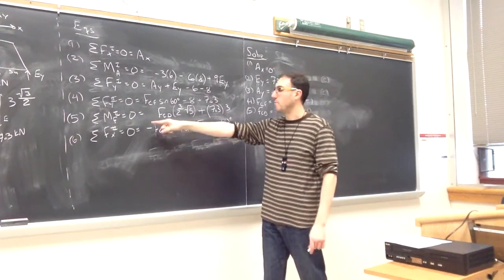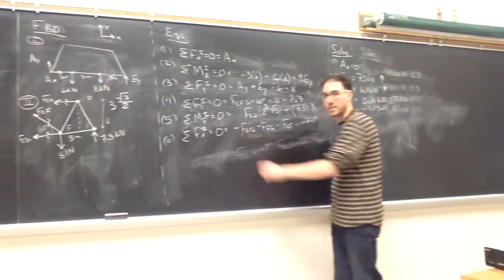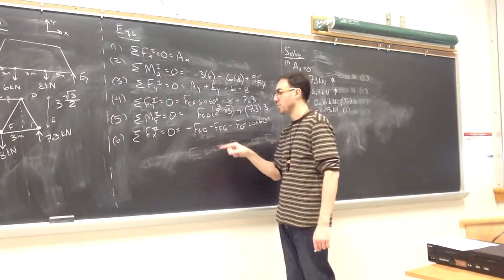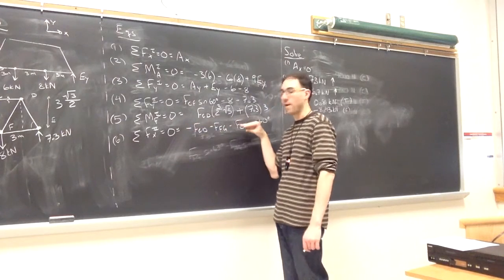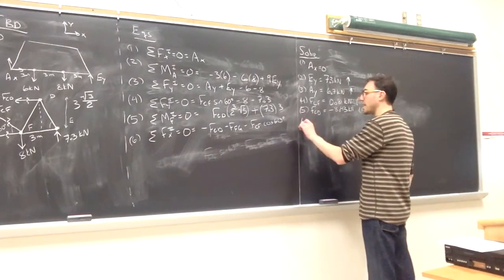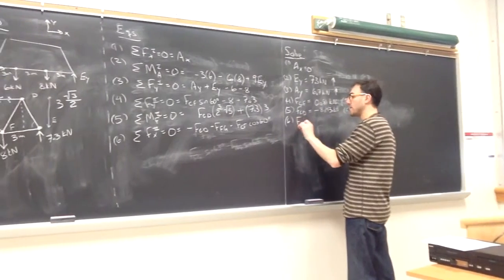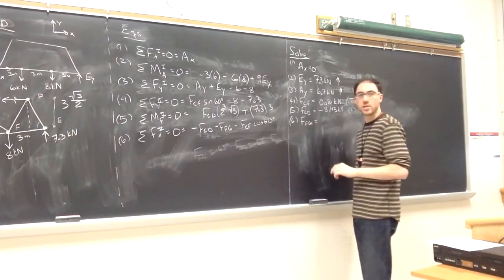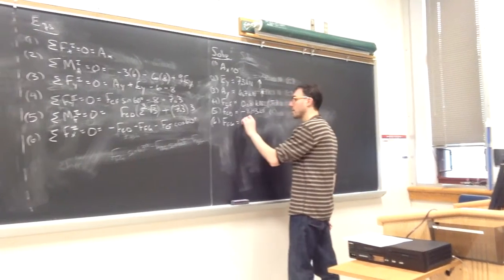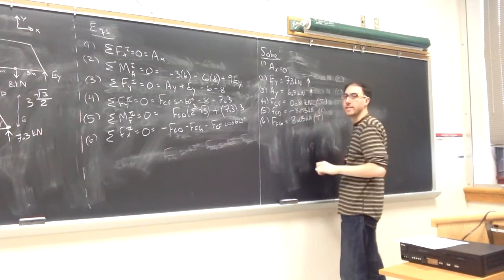So when I put it into here, it'll be a negative times negative 8.43. So this will actually become a positive 8.43. Keeping track of the sign on things is the tricky part here, and that's why I always write it first as the variable, then put in its value later. So if we put that in and we put in our value for CF, then the last thing we don't know is FG. And we can solve for FG, and that's where I get a positive 8.03. And that should then be in tension.